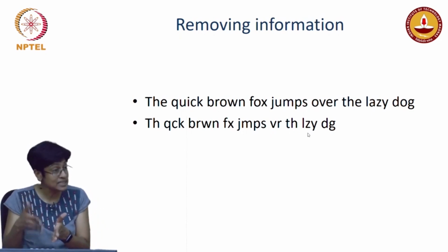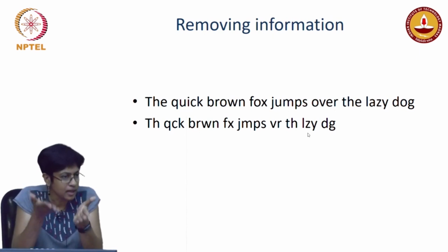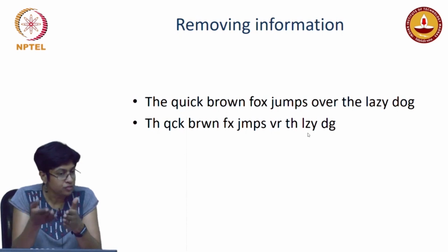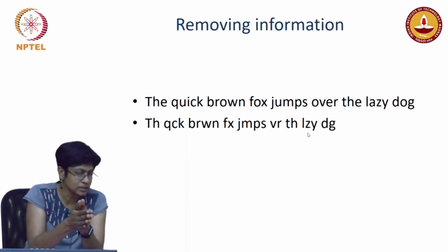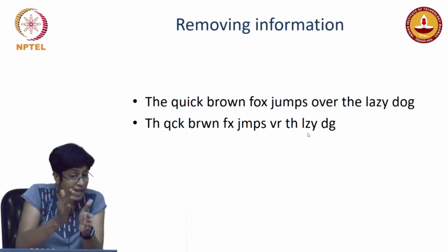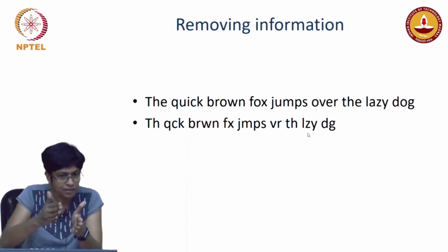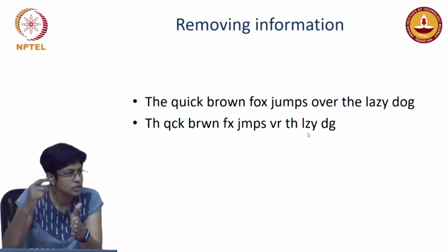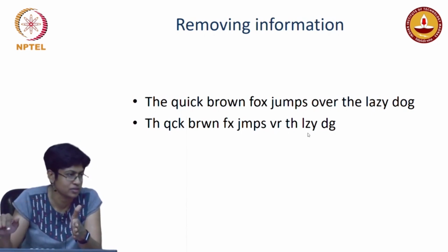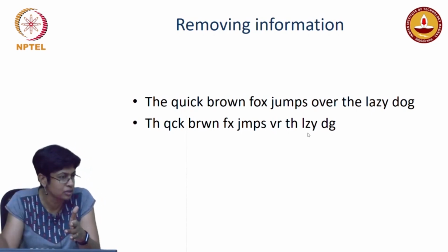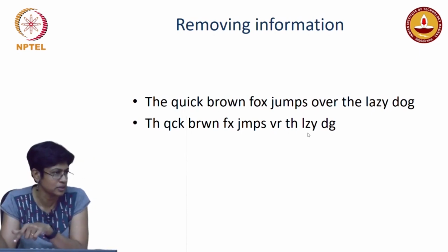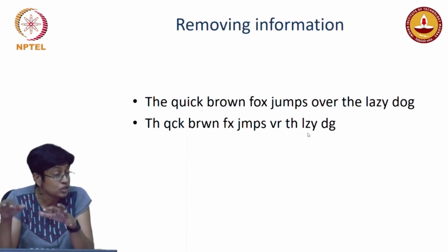And so yes, we did analog to digital, but you could reduce the amount of information by saying, well, if the eye is sensitive to some color at some intensity, and you have certain intensities for some time on the screen, and immediately thereafter you have a lower intensity or a different color, you could remove those because your eye is not sensitive for some time after that. If you hear a certain frequency for a certain time, for some moments after that, you won't hear other frequencies. So you can filter out those frequencies and we have not lost anything.